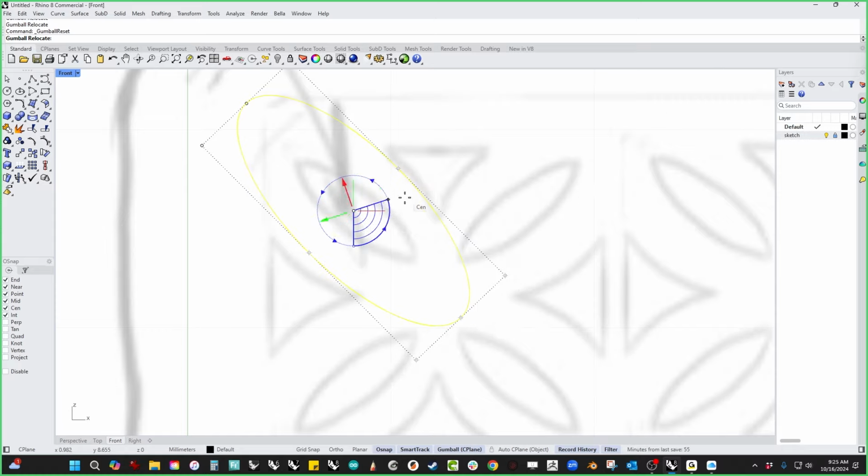And I like that because with the O snaps enabled, if I do that same thing, it's going snap, snap, snap, snap, snap. Settle down. Somebody had too much sugar cereal. Especially if you've got a lot of geometry on the screen, it'll give you a seizure because it's always looking for stuff. So I always shut that off, disable it, and then just use the Alt key in order to enable it when I need it. And on the Mac, that's the Option key.